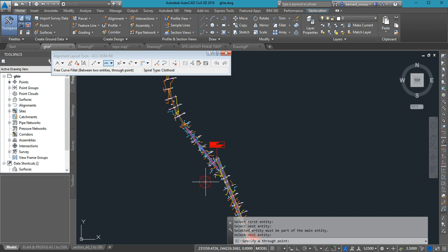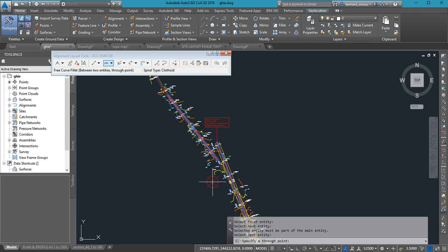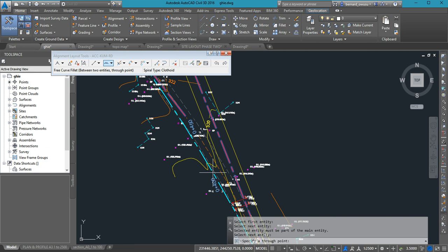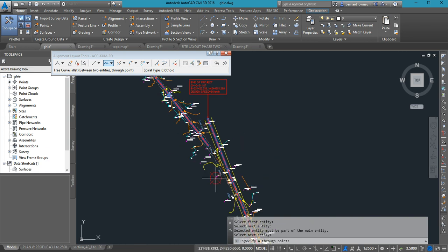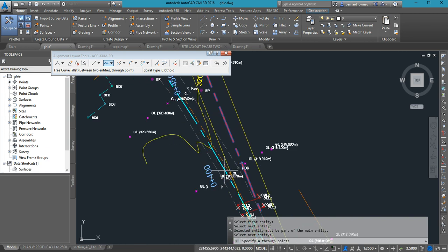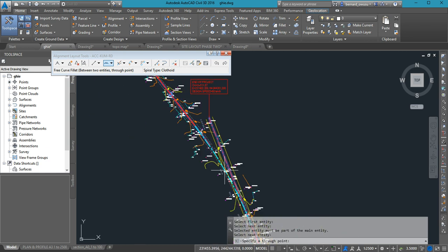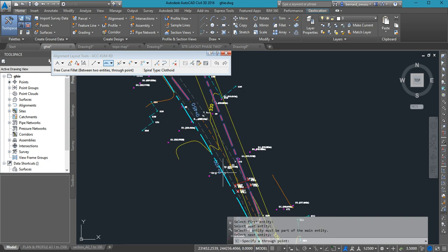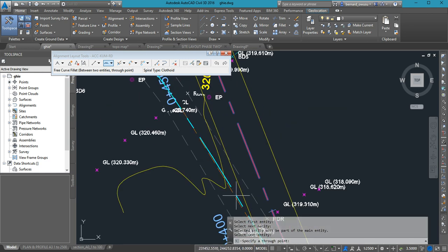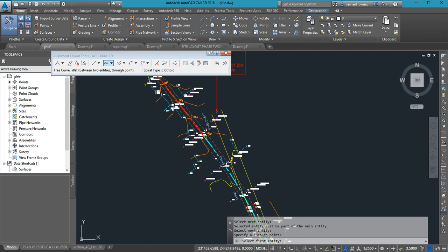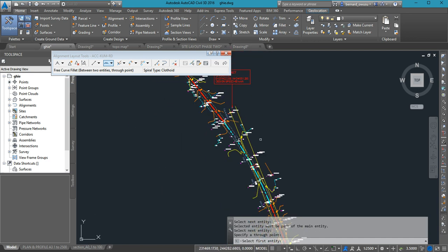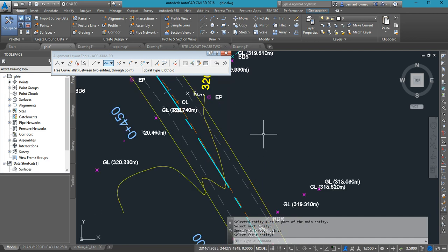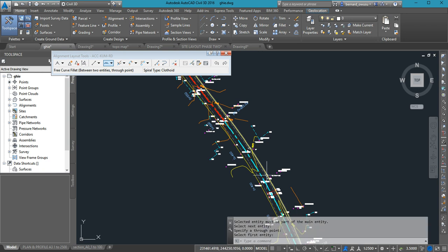It's a curve. Depending on where you are, it should be downward because the deflection is that way. It should not be up. It should be here. Please, do you have something like this? Yes. So tell it, where do you want your curve to pass? I want mine to pass somewhere here, so I click. Then that is it. So I have my curve. When you finish, you right click. And you have everything continuing up to the end of the second tangent.